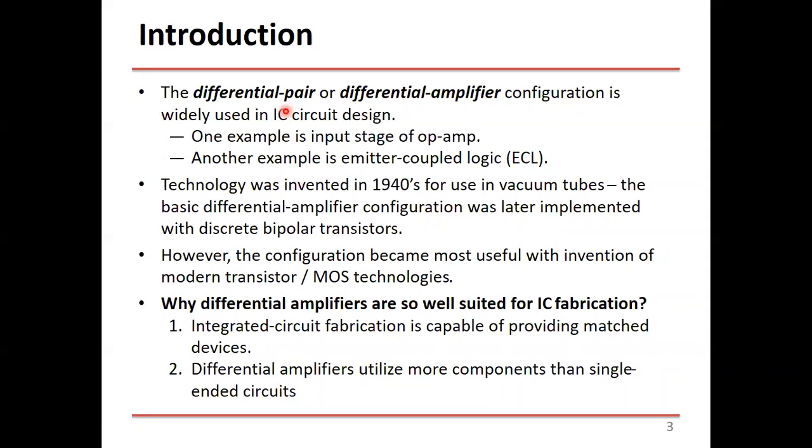Also in logic circuits, in digital electronics, instead of using a single transistor as a logic gate, like an inverter or an AND or OR gate, we use a differential pair, two transistors, to improve the performance of the circuit. So the differential pair is useful in these two examples, in the first stage of an operational amplifier and in some logic gates, what we call emitter coupled logic gates.